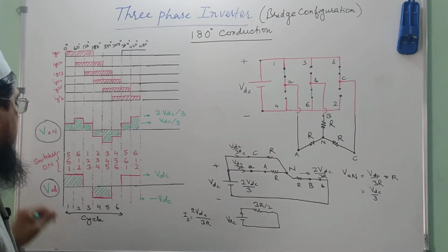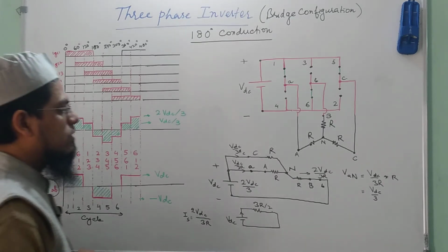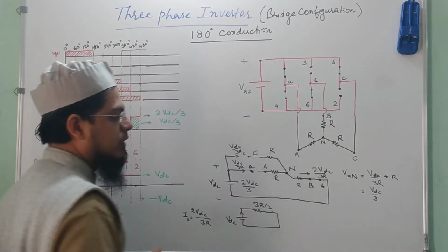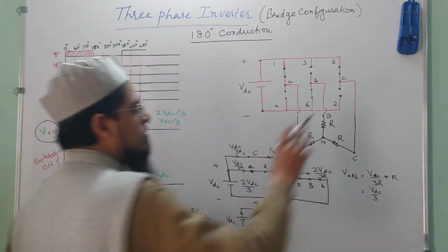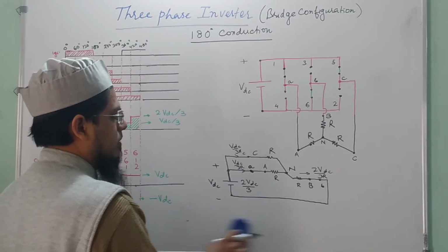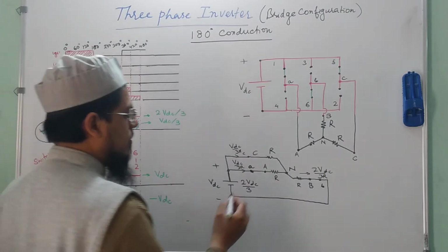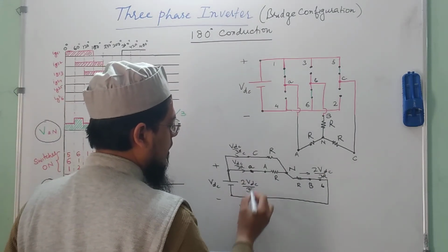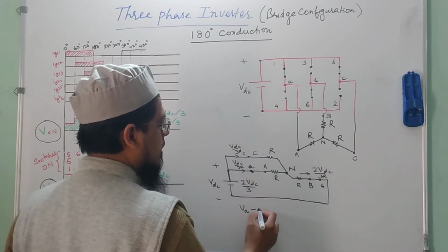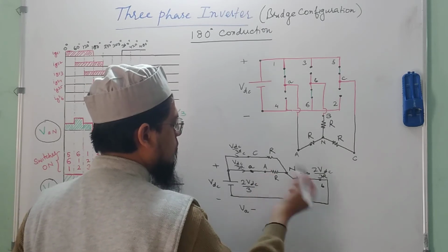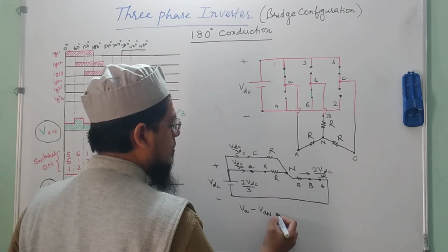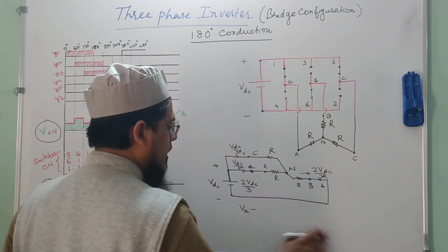Okay. Now, what about the line voltage VAB? So that means the voltage from here to this point. Okay. Let us try to find that out also. So let me start from this point. Let me call this VA, and then there is a drop here. Since I am going in the direction of the current, it is minus of the drop. So the drop is VAN. So this is VAN, and then there is a drop here also, or just let me write down the values itself.